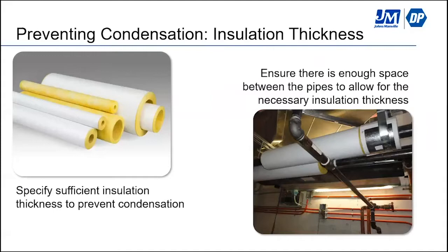And then once you've got the specification determined for that thickness, you have to make sure that the conditions allow for that insulation to maintain its thickness in all the areas that it could be installed. So that's where your contractor can help you identify or troubleshoot some concerns if there's a risk of not being able to maintain full thickness.